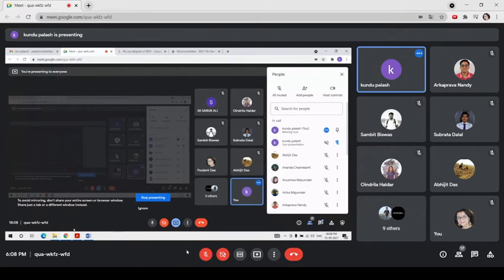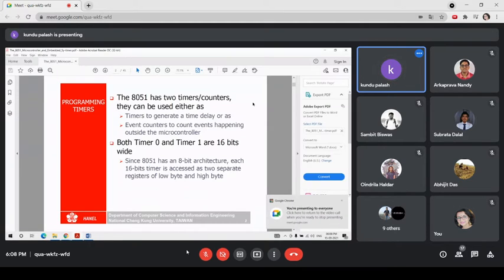Yes, that's right. So again, I am repeating what I have told. What is a timer? A timer is an electronic device which will generate the timing signals. A timer is based on the basic timing signals, that is, the clock signals. There is a binary counter, which will be incremented up or decremented down. That is, there are two modes of the counter, the count-up mode and the countdown mode, that is, the down counter or the up counter.